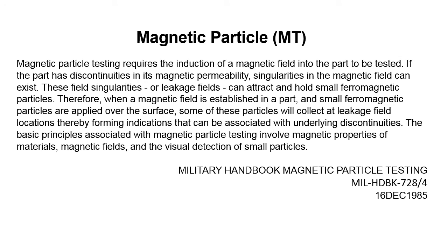Magnetic particle testing requires the induction of a magnetic field into the part to be tested. If the part has discontinuities in its magnetic permeability, singularities in the magnetic field can exist. These field singularities, or leakage fields, can attract and hold small ferromagnetic particles.